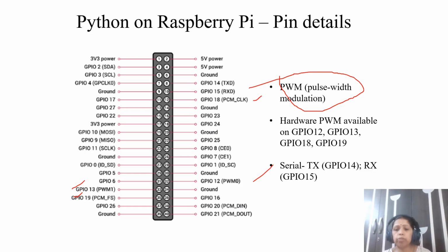If you want to send analog data or receive an analog value, I will discuss this in the upcoming lecture, you need to connect those external devices to the PWM pins, GPIO pin 18, 19, 12, and 13. Normally, if you want to use analog write or analog read, the PWM pins are used, and for digital read and digital write, you can use any other GPIO pin.